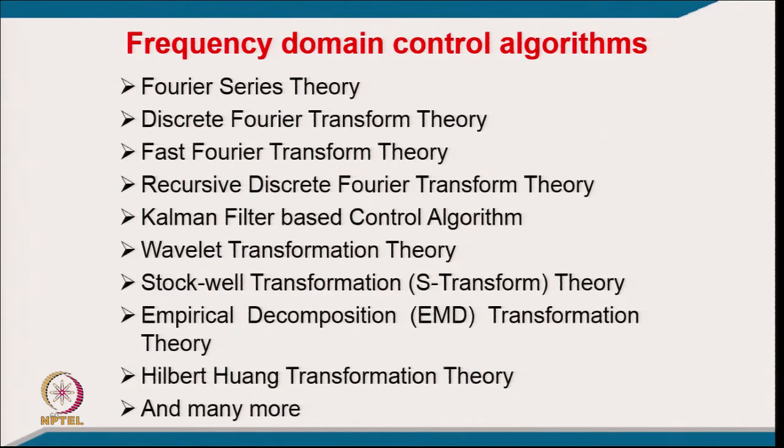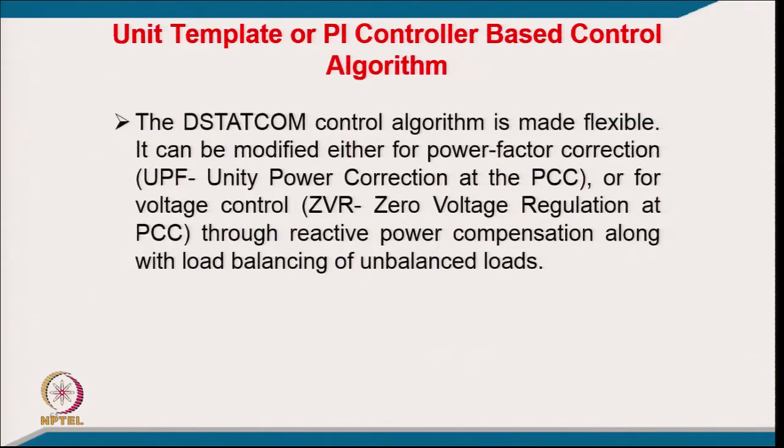So, we would like to discuss a couple of them, of course; we can't discuss all of them. We discussed many of them already earlier in DStatCom, but here we would like to discuss only a couple, just to give you an idea how they are. So, starting from DStatCom theory, it is made flexible; it can be modified for power factor correction or voltage regulation, zero voltage regulation through reactive power compensation with load balancing and harmonic elimination.